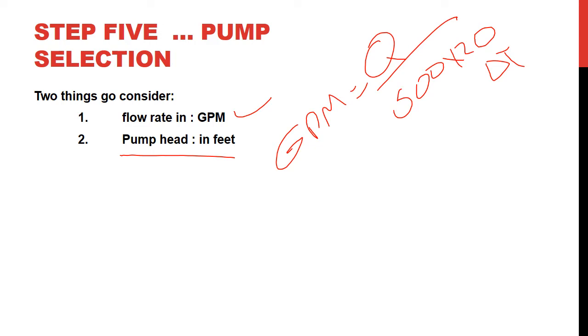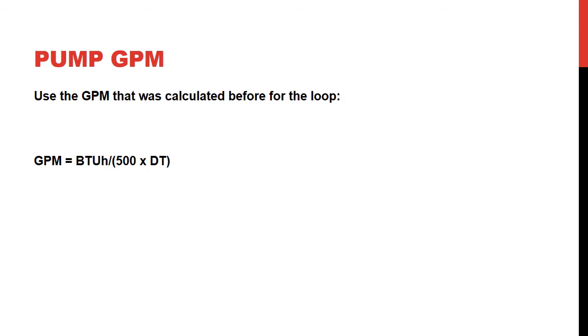What is pump head? Pump head is pressure. How much pressure can that pump provide? Why is it in feet? It's just a unit. We can convert that to Pascal or PSI, but feet is more common for pump selection, especially in HVAC. Okay, so GPM, again, this is the equation, and we get that.